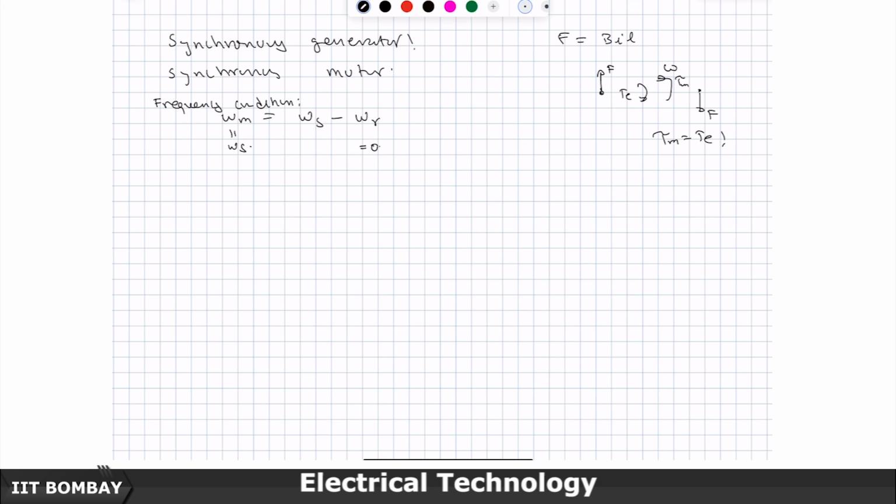So control systems are required, and many things you will come to in the electrical power systems class later on. If Tm minus Te is not zero, then J, the moment of inertia, times d omega by dt should be equal to Tm minus Te. When Tm is equal to Te, then omega becomes constant, which is our synchronous speed at which we get the necessary things going on.